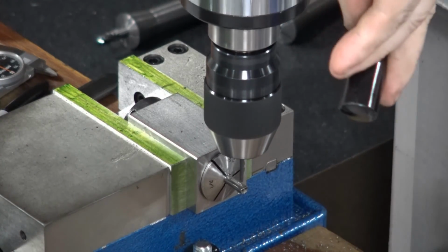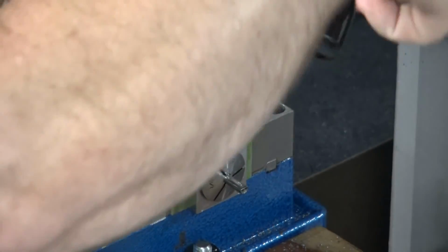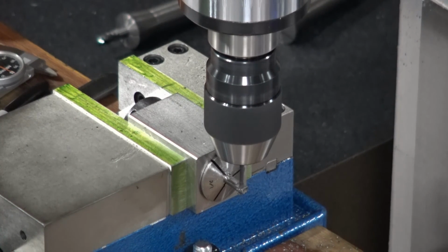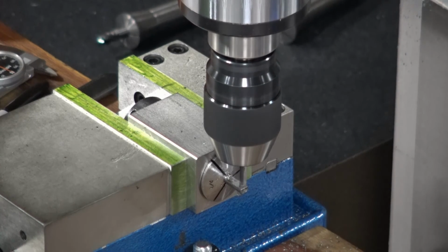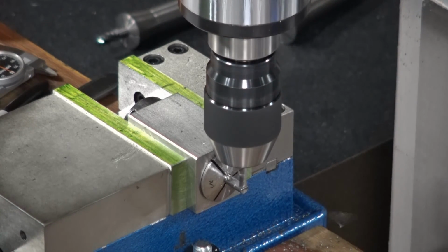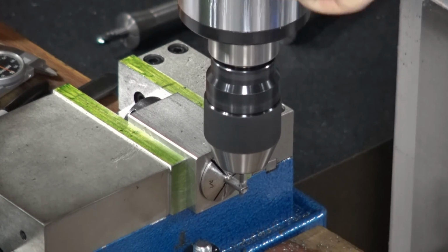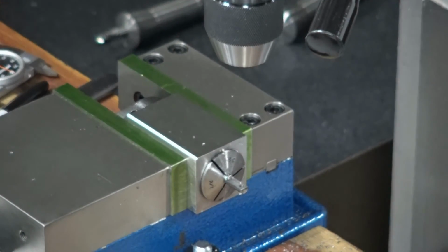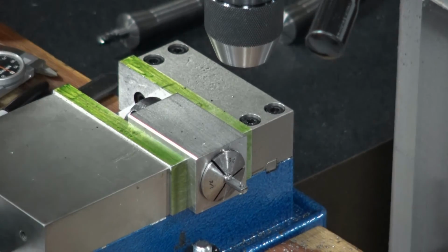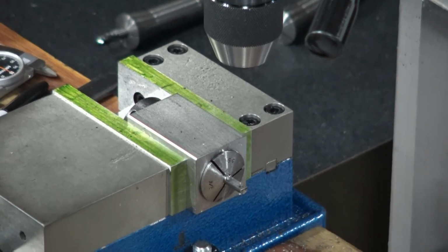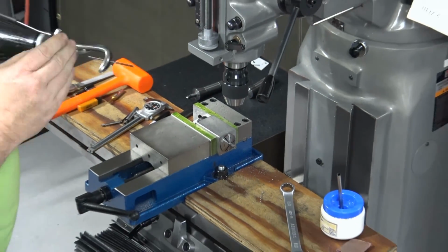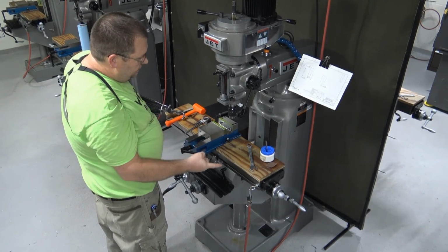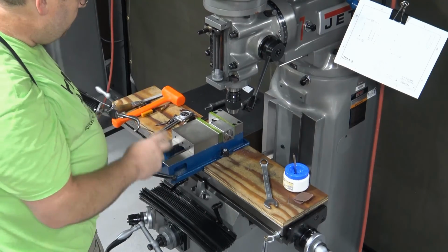We're going to drill all the way down through. Let me move that position so you can actually see what's going on. Well, these number 32 drills really cut nice. Remember, we've selected that drill bit to be 8 to 10 thousandths under my reamer diameter. What's my reamer diameter? My reamer is 126. That allows me to hit the tolerance of 126 plus 2 thousandths, minus nothing. What do the reamers do? Nice precise hole, nice round hole, gives me a nice finish down inside.